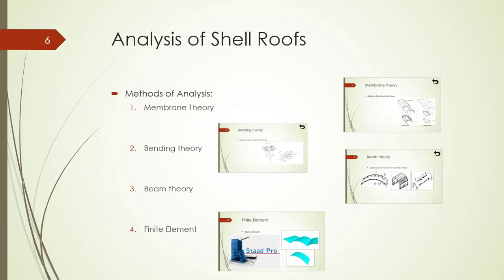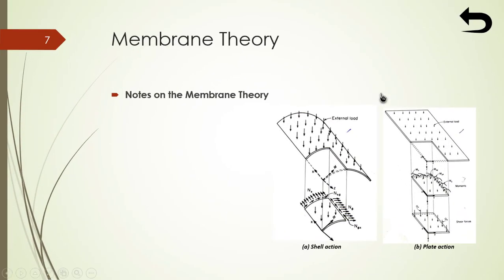The stress analysis of the shells. Elastic behavior is usually assumed for shell structural analysis, with a suitable assumption to approximate the stresses. The stresses usually determined by the membrane theory are assumed constant across the shell thickness. The membrane theory for shells, however, neglects the bending stresses, yet every shell is subjected to bending moments, not only under unsymmetrical loads, but under uniform and symmetrical loads. In the membrane theory, the shell is idealized as a membrane incapable of resisting bending stresses. An example of a pure membrane state of stress is furnished by a circular pipe subjected to fluid pressure.